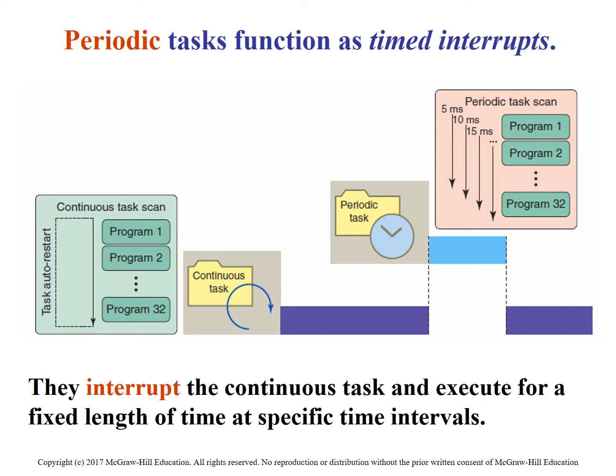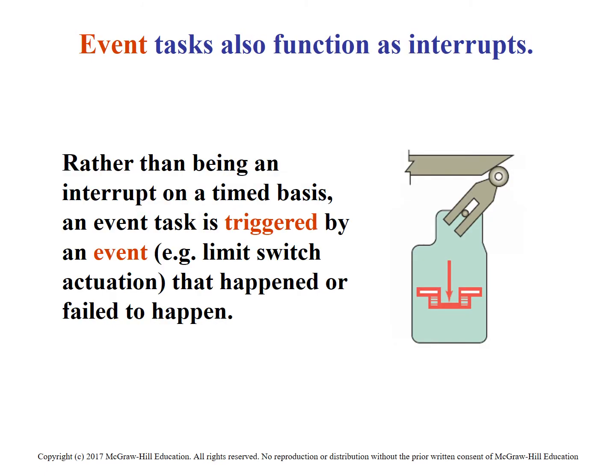So they're going to talk about periodic, where you can set up a time base or interrupt or something of that nature. I'm not going to get really too involved with it because most of the time you're not going to be using any of these tasks. So I'm just going to make you aware of it, that you can make it so each one of these programs is called at a different time. You can also have them set up as an event, so when some input takes place, it triggers that subroutine to take place.